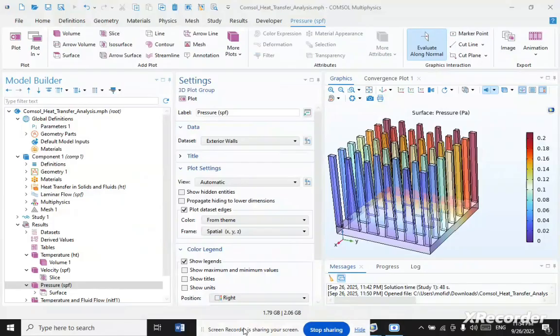The present review systematically analyzes different aspects of micropin fin. For example, its cross-sectional shape, arrangement density, and also design parameters. The design parameters, including aspect ratio, side wall gap, tip clearance, and etc., were thoroughly described and their optimal ranges were elaborated.